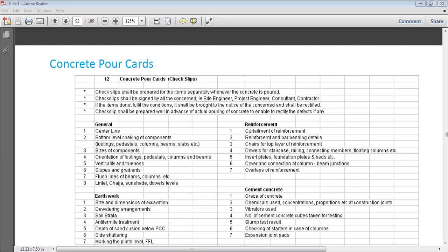No, there may be black cotton soil at the top, a different kind of soil in the middle, and at the bottom a rock, murum sand or murum nature of soil. We don't know what is there in our earth crust. When you start to excavate, at that point only you get to know the nature of the soil, and based on that you have to take some tests: the standard penetration test, tests related to the physical and mechanical properties of the soil, swelling test, plasticity index, liquid limit, OMC, MDD, percentage compaction, shear strength of soil, confined, unconfined, whatever it may be.